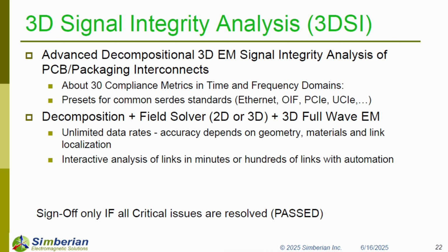So I will show how to save and load a standard. It uses again decomposition, a field solver for either two-dimensional field solver Simbeor SFS, or for transmission lines 3D electromagnetic solvers can be used, 3DML or 3DTF for packaging interconnect specifically.